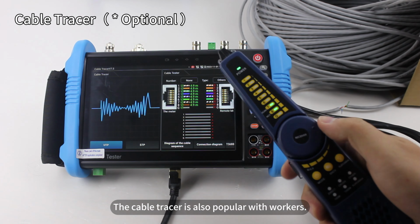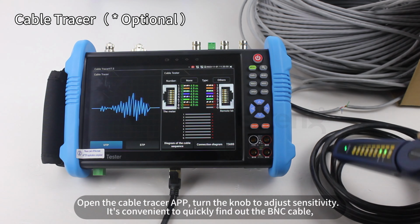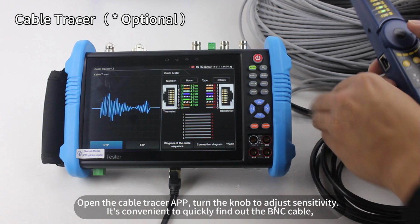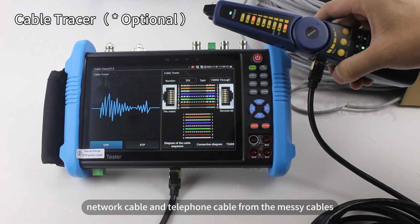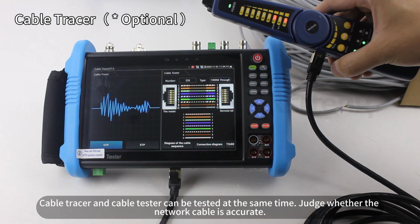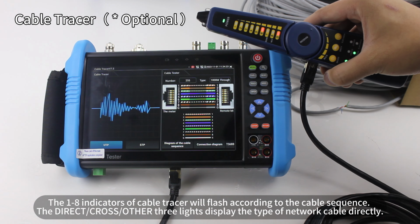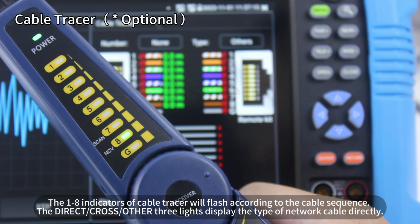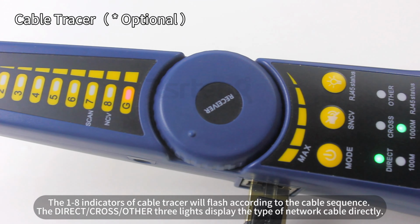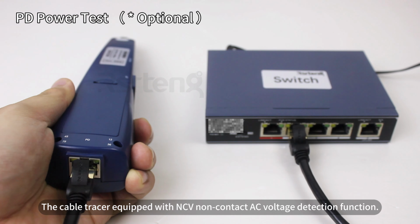The cable tracer is also popular with workers. 1. Open the Cable Tracer APP. Turn the knob to adjust sensitivity. It's convenient to quickly find the BNC cable, network cable, and telephone cable among messy cables. The cable tracer and cable tester can be used at the same time to judge whether the network cable is accurate. The 1 through 8 indicators of the cable tracer will flash according to the cable sequence. The direct, cross, and other 3 lights display the type of network cable directly. The cable tracer is equipped with NCV non-contact AC voltage detection.